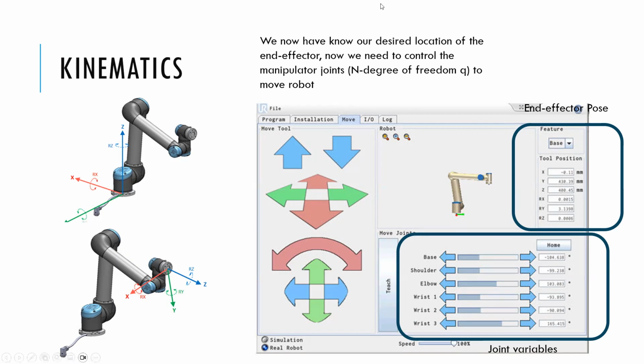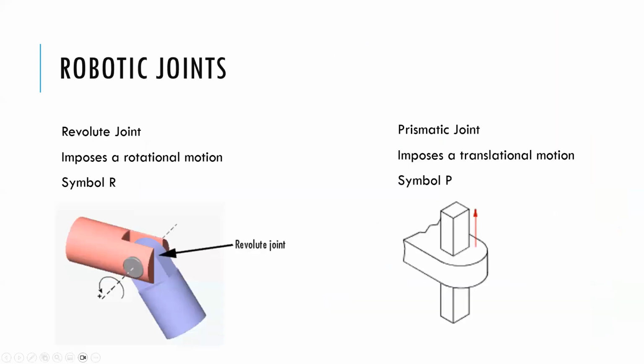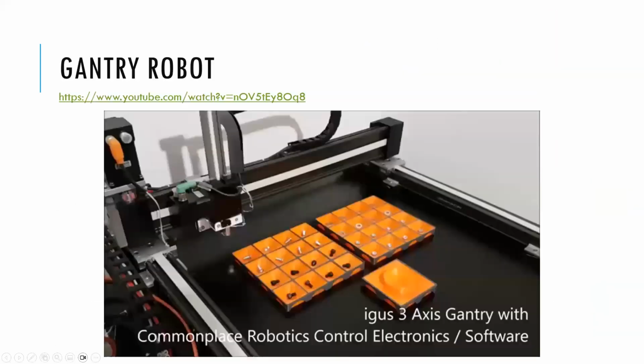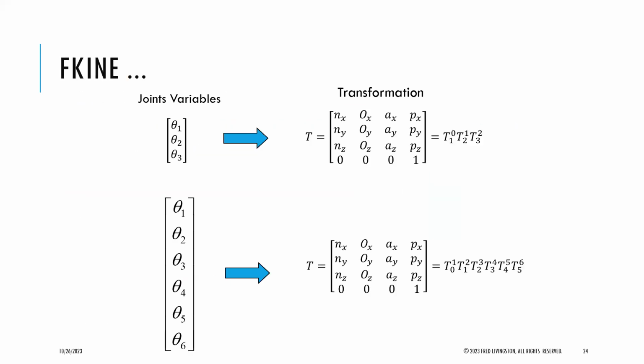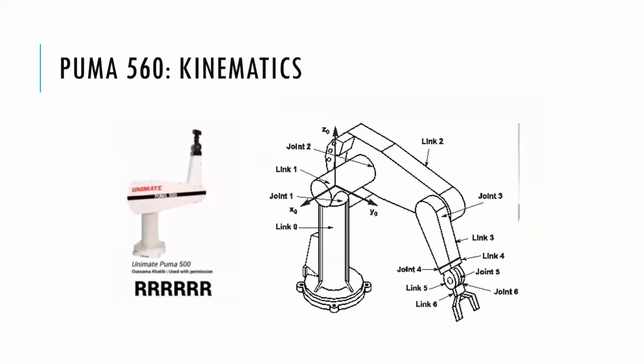So if you were to custom build your own robot system, say by 3D printing or making these, you know the links of this here. If you wanted to figure out the position, you could just do this. You could figure out the kinematic chain of that and do the dot product there, and you have your forward and inverse kinematics for your custom machine or custom automation equipment, and you could go to different positions by just telling that servo motor or whatever to rotate to that position. And so that's kind of where we're going with that for this course. So look forward to a homework assignment on that for the next class.